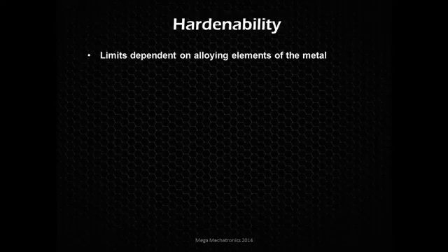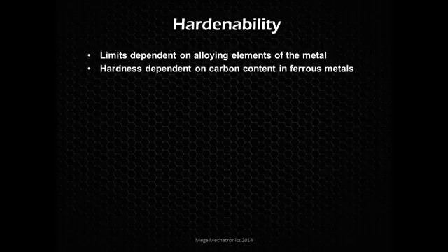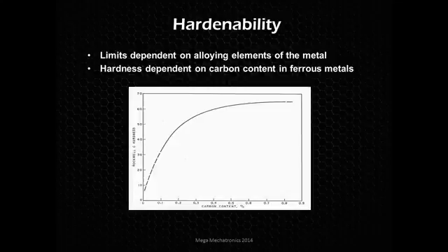And the concept of hardenability: different alloys of metal are going to have different abilities to harden, a different max hardness that you can achieve. So with ferrous materials, we put carbon in it, and the carbon will increase the strength. It gives certain characteristics to this crystal structure as it's in there. It deforms it in a certain way and allows us to harden that material by controlling the crystal structure. So looking at this chart, we have hardness versus carbon content. You see the Rockwell C hardness scale goes up as the carbon content goes up.